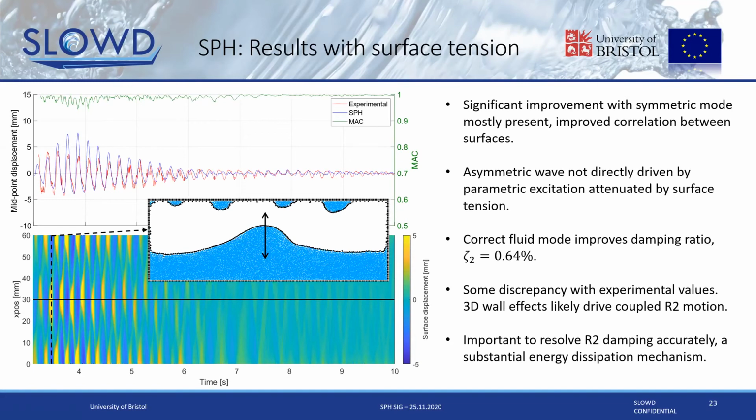But what we've seen here is that surface tension greatly improves our free surface response, because we are attenuating those nonlinear breaking waves, and it allows us to set up our resonant conditions in our fluid, improving our overall fluid-induced damping.